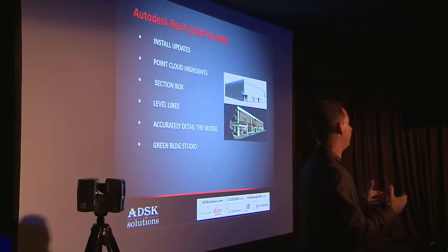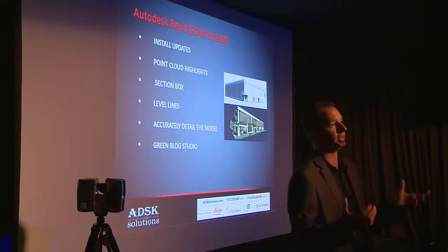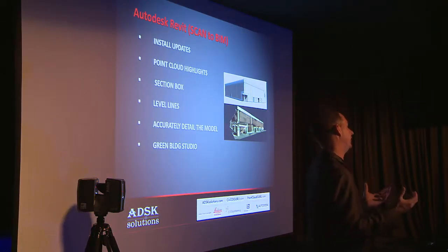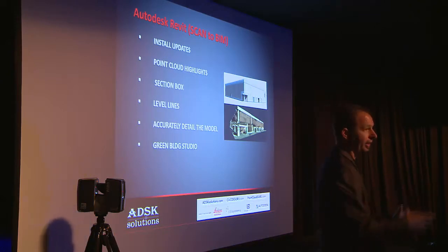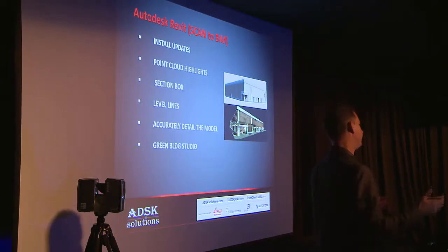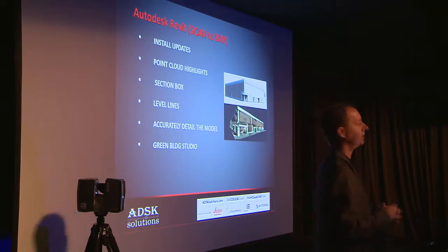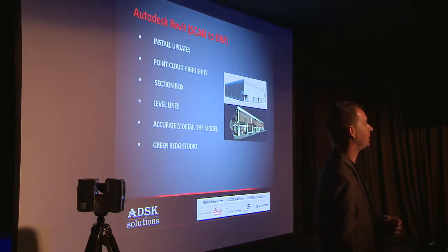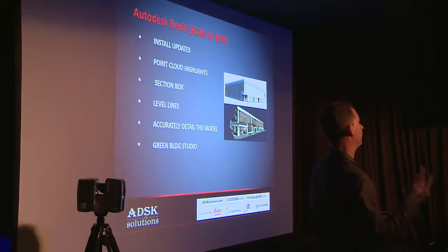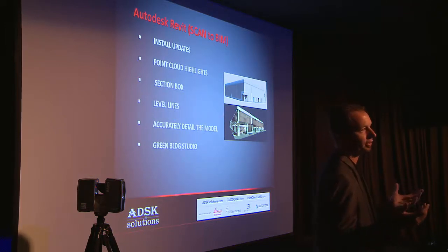But my goal, if you guys get this done before me, more power to you. I keep talking about it forever, so I want to share it. Taking pictures of a manhole, right? Just something simple. We have all the inverts, all the problems of getting that data. You just snap pictures on a stick all the way down, pictures back up. You should be able to create a point cloud of that. The big thing is you need some lighting down there in order for that to work.